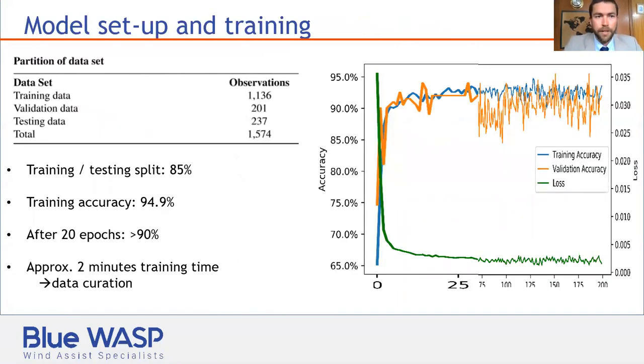So the model setup, there's an important distinction to make between observations and features in the training data. An observation would be, for example, one ship speed, one ship hull, leeway angle, and beta, so a combination of operating conditions. On the other hand, features are the information within the observation itself. In the case of a RANS CFD run, the mesh was about 7 million cells. So in principle, there are 3 velocity components and a pressure in each of these cell centers.